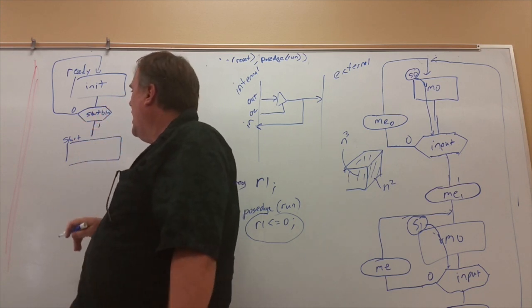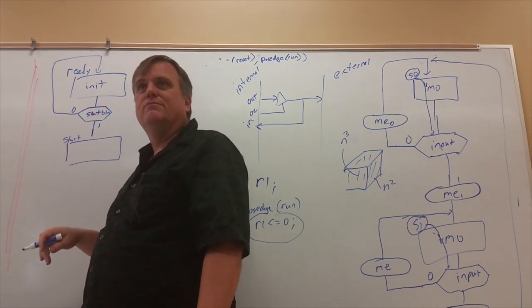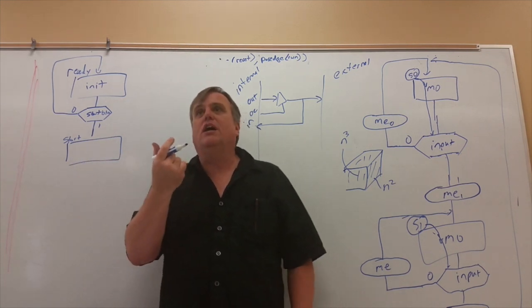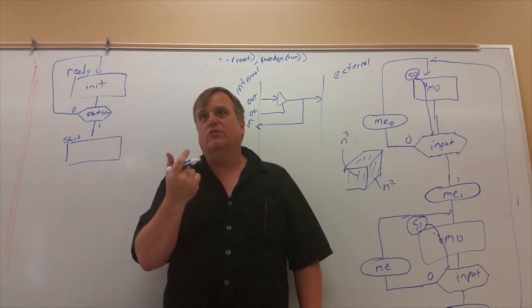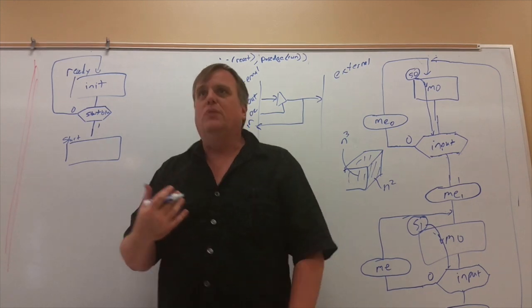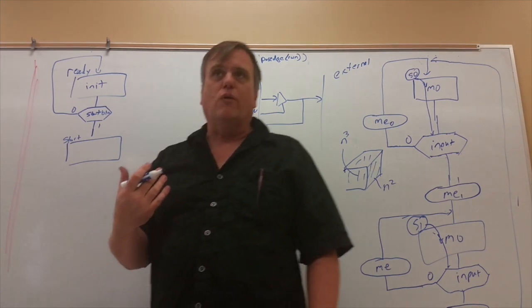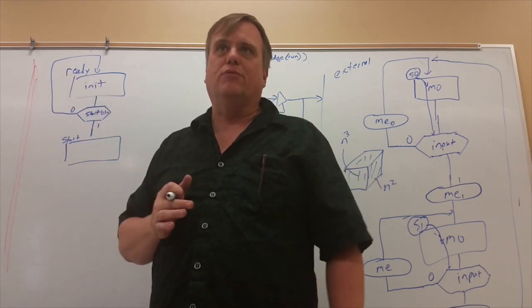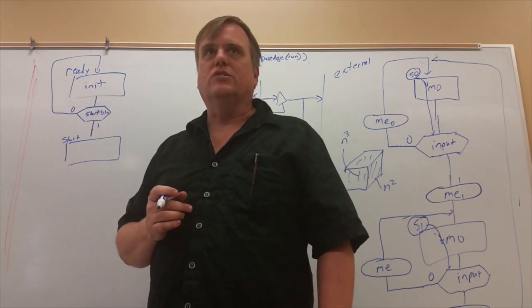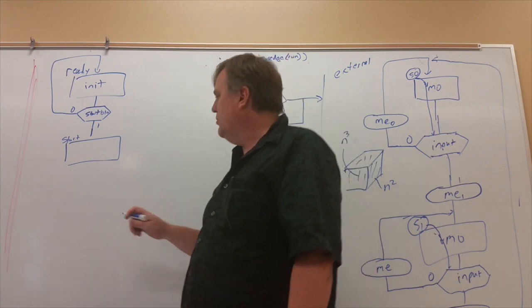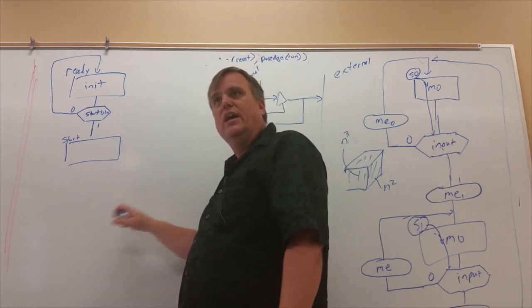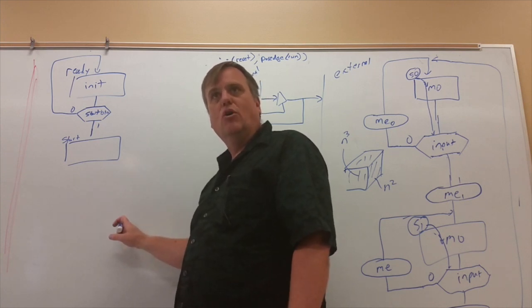How does it implement that when you synthesize it? There are pre-done random number generator circuits. The most common ones are what are called pseudo-random numbers, and this depends on what libraries they give you inside Xilinx for synthesizing them. The typical pseudo-random number generator takes a number of states, and they've got taps off of them.